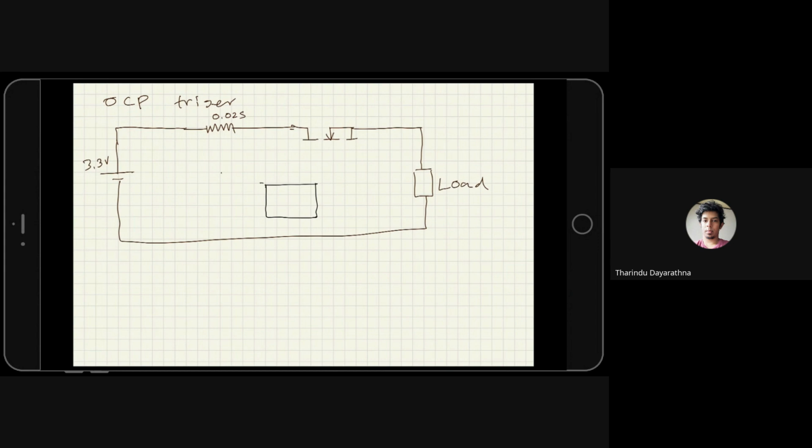It measures the voltage drop across this resistor. Okay, V drop, or we can say V sense. It measures the voltage drop across this resistor. Okay, you need to remember the current coming in this direction is almost zero. Very small, like nanoampere current coming. You have to remember that one. Both lines are not taking too much current, it's just sensing the voltage. Okay,